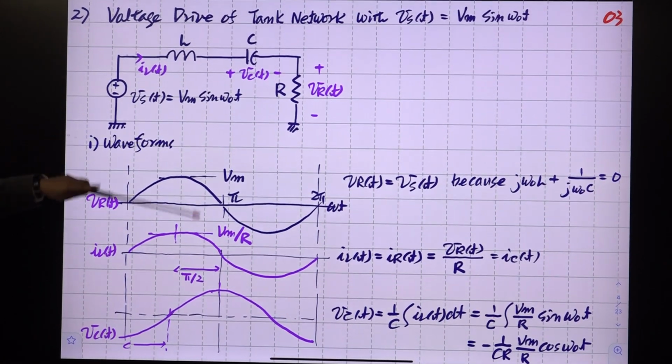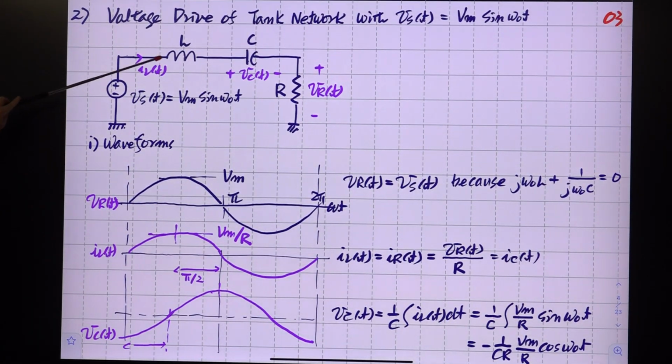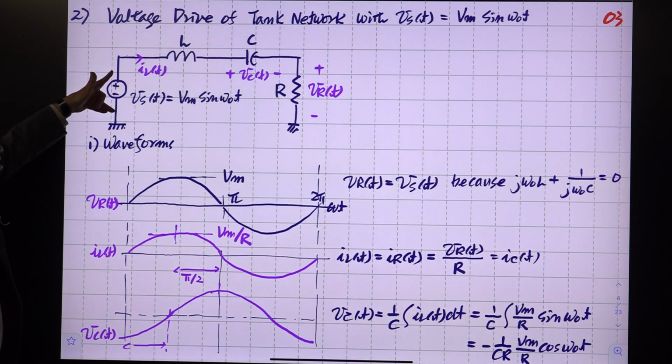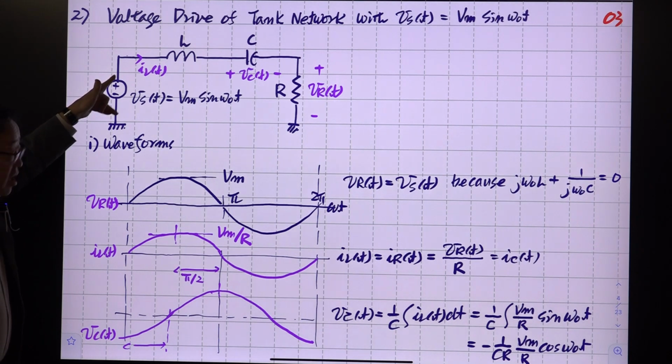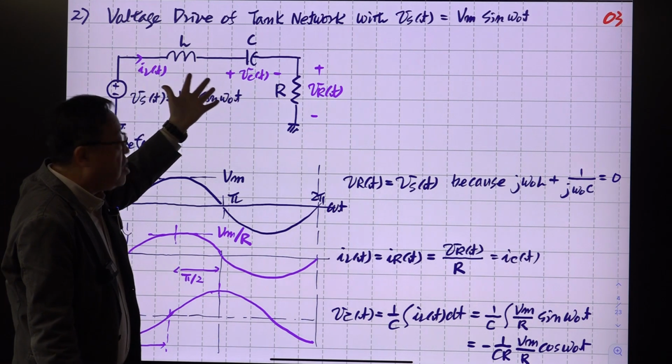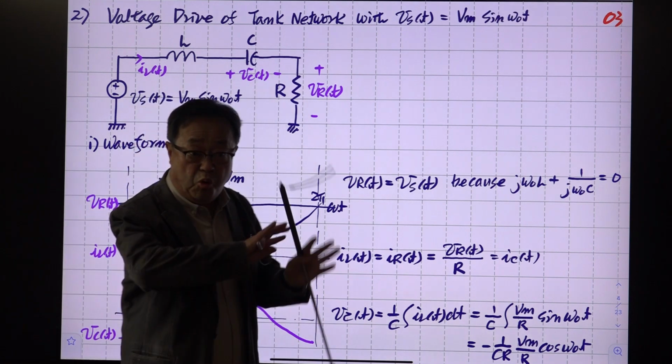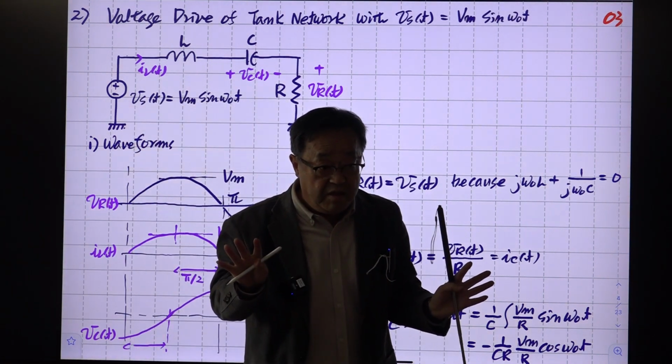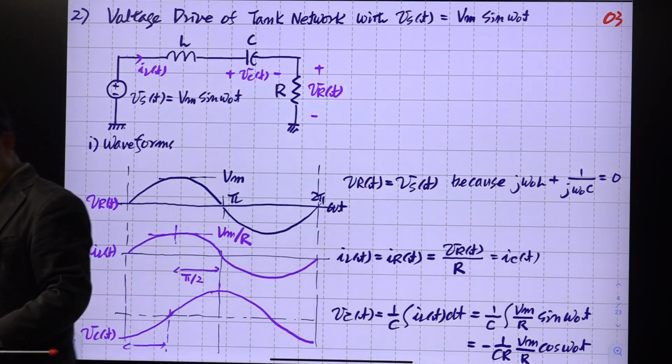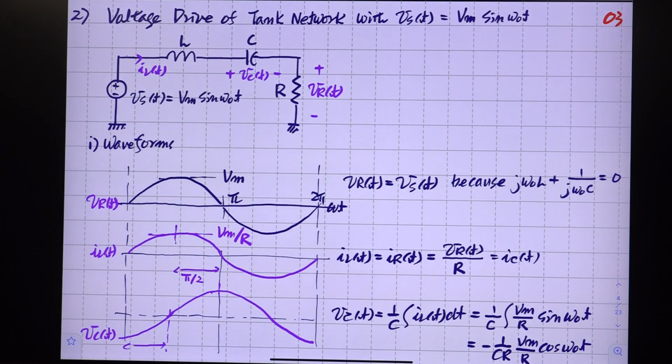The RLC series resonance circuit should be excited by a voltage source, and each of these three components works as a voltage divider. A parallel resonance circuit should be excited by a current source, and it shares the current; they decide the ratio of the current at the node.